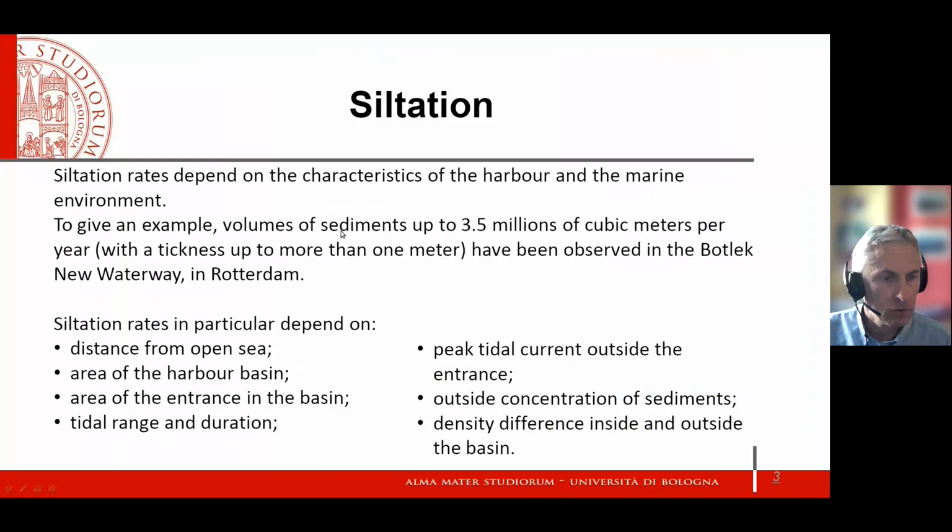Now, what is influencing the siltation rate? Siltation rates in general depend on the characteristic of the harbor and the marine environment, of course. They depend on the flux of sediments along shore and across shore. They depend on the hydrodynamic behavior of the marine and harbor environment, and also they depend on the climatic condition.